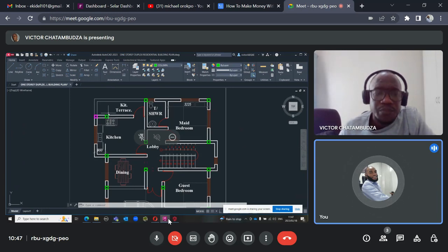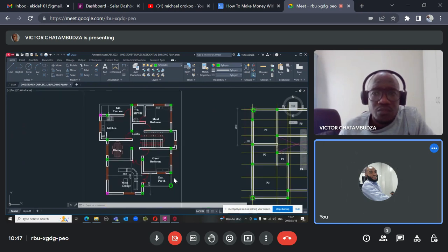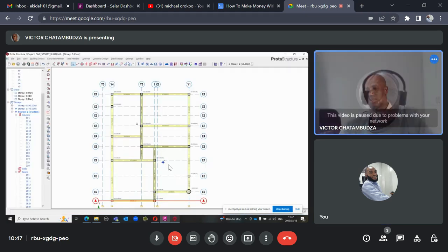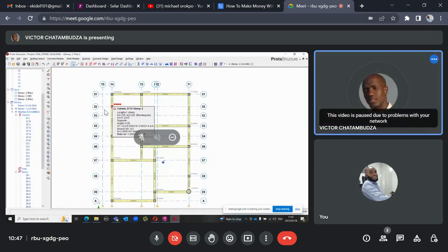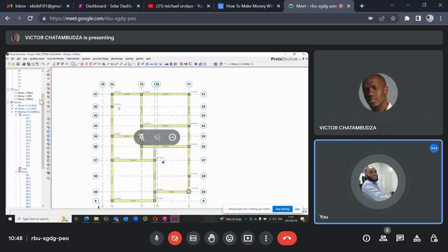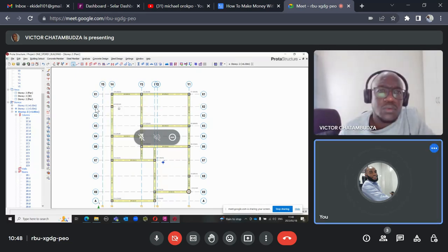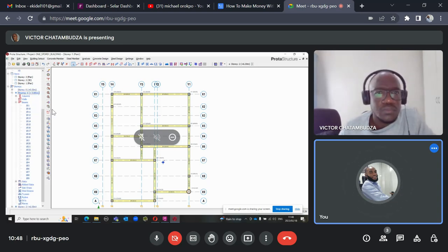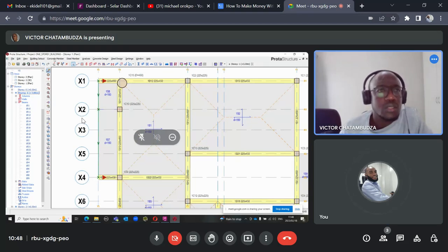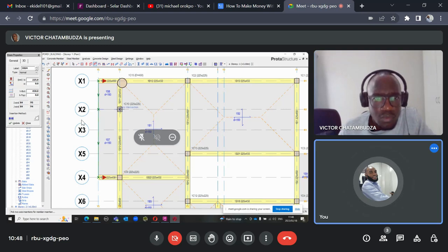Okay, let's model it first. Go back to your plan view, your model. Okay, so we are here. Yes, so we're going to move the cantilever coming here. Go and put the cantilever beam on the ground floor, not on this place. Ground floor first, to be able to carry the column that we're going to put there. Story one, yeah, story one. Put the cantilever beam there. You can take the beam property, any of them. Now put it from that point coming out.